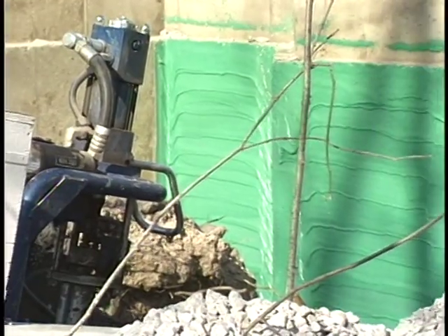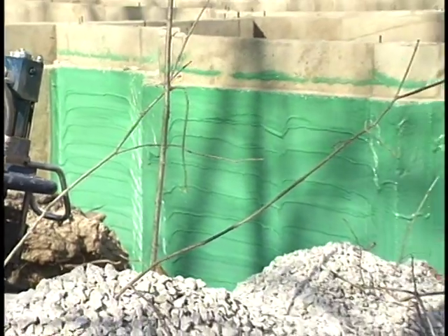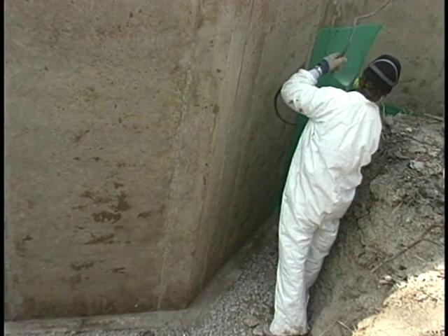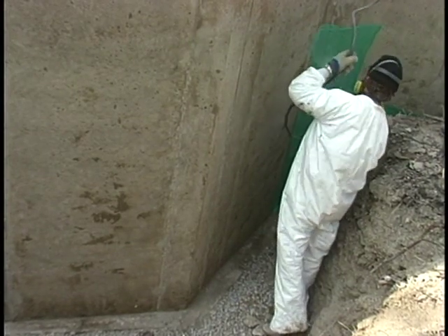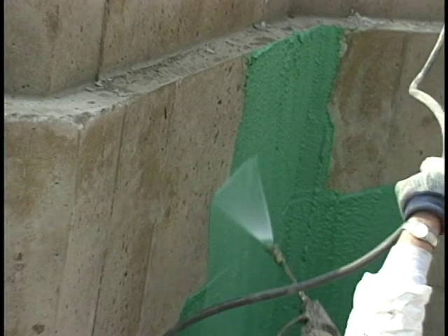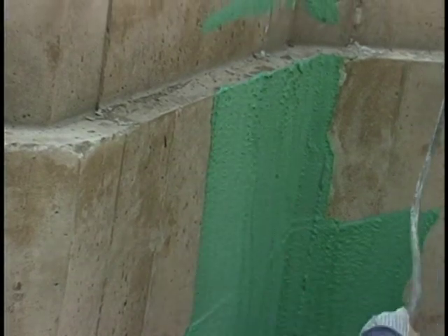Most builders waterproof foundation walls to prevent water or moisture from seeping into the basement. Either an asphalt, synthetic rubber, or plastic-based material is applied to the outside of the wall before backfilling. Asphalt and synthetic waterproofing compounds are often sprayed onto the foundation wall.